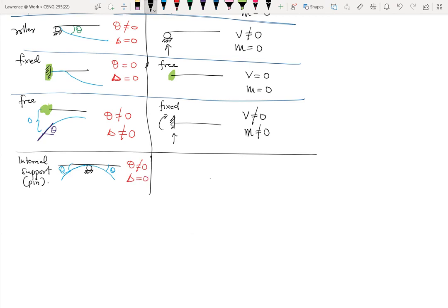So to have a similar behavior, it means that we'll have a beam with what we call an internal hinge. For an internal hinge, the shear is not equal to 0, but the moment at a hinge is 0. So they satisfy the conditions we need to be able to find our moments and shear, which correlate to deflections and then the slope.